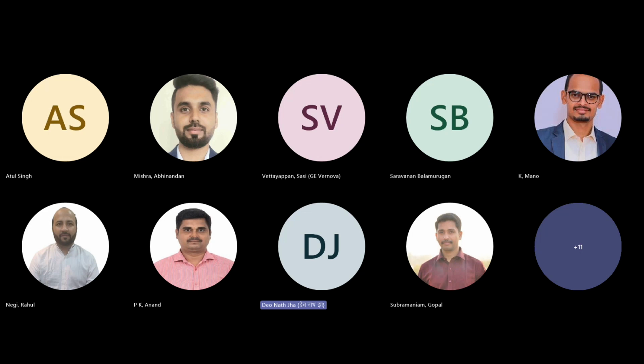But when we want to go for a mechanical model, it is better to make it a data driven model, because then you can have data from multiple transformers of the same design or sister units, which can feed the data to develop a mechanical model of a transformer or a dielectric model. And then there can be knowledge based events like weather patterns or grid related conditions. So there will be some amount of inaccuracy within a digital twin, and as the data grows over a time period, the accuracy will improve further, because the model will train itself against the inaccuracies observed in the past.